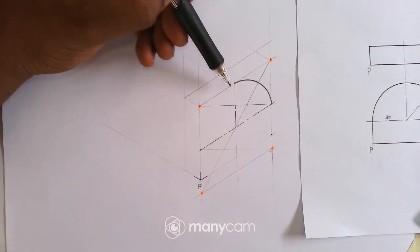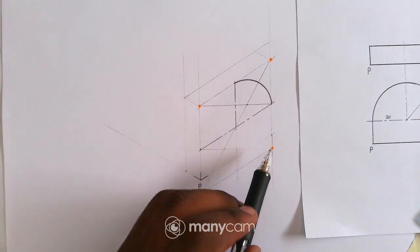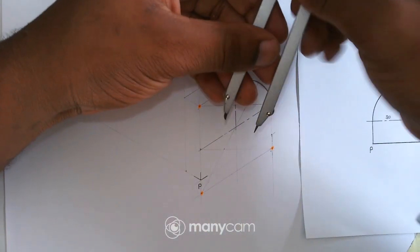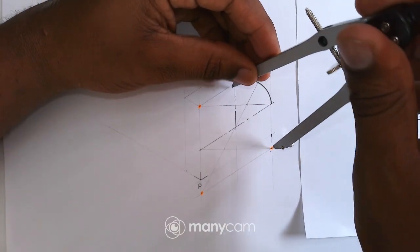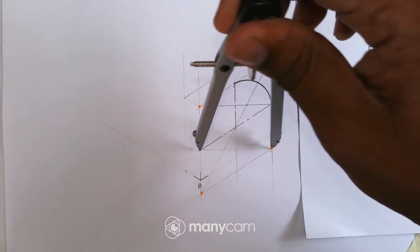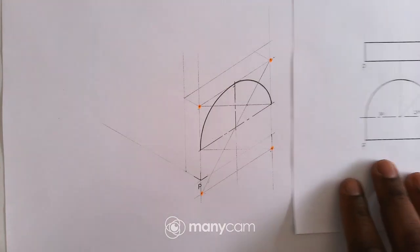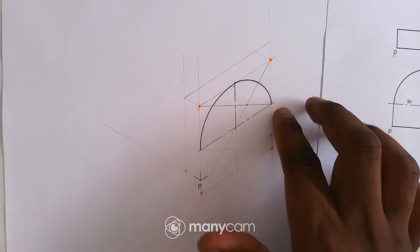Okay, so now I'm left with this part on this side. For this part I have to put my compass there and open my compass to that point, and then draw the arc. So I take my compass, put it at this point right there, to that point up there, and then obviously I draw an arc like that. So now I have this arc right there. This is the isometric arc, right?